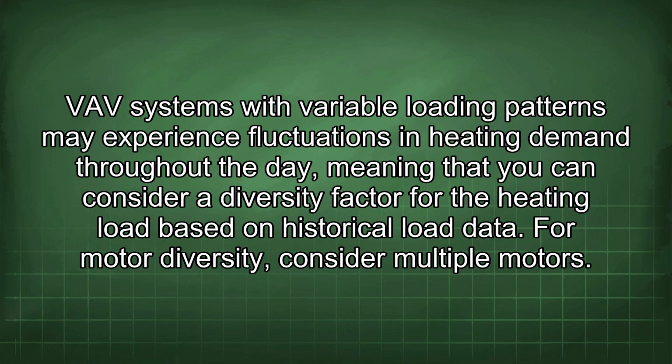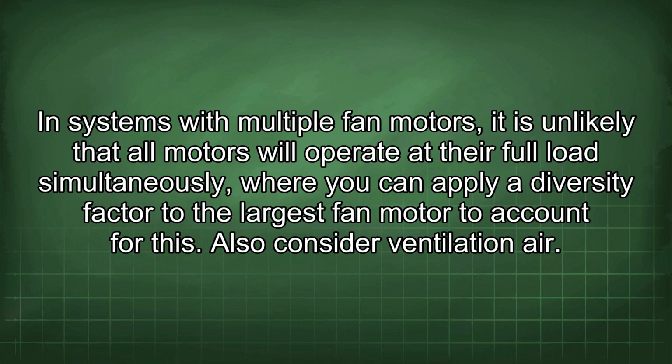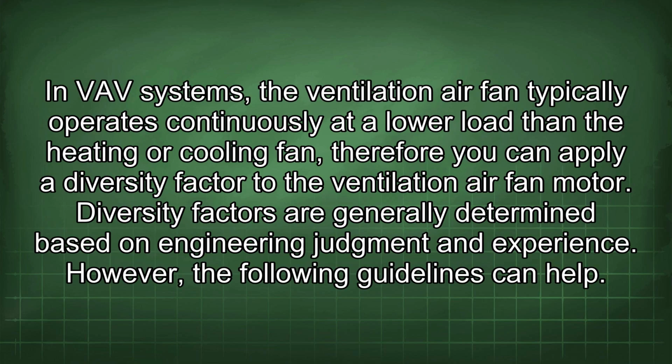For motor diversity, consider multiple motors. In systems with multiple fan motors, it is unlikely that all motors will operate at their full load simultaneously, so you can apply a diversity factor to the largest fan motor to account for this. Also consider ventilation air. In VAV systems, the ventilation air fan typically operates continuously at a lower load than the heating or cooling fan, therefore you can apply a diversity factor to the ventilation air fan motor.